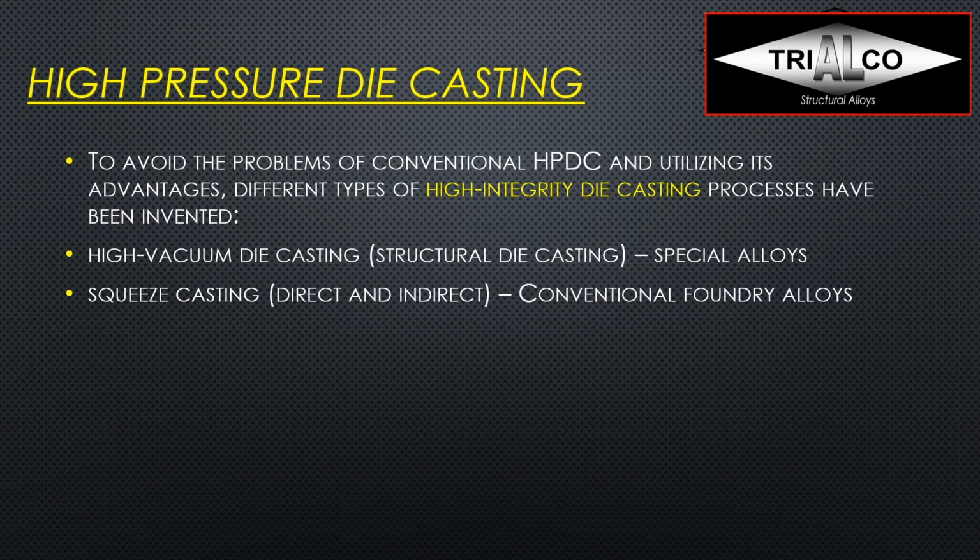And then we have the semisolid casting. There as well, you can use conventional alloys, but the beauty of semisolid casting is actually that we can cast different types of alloys as well that are much more difficult to cast. Semisolid is really just the way it sounds. You have a certain solid fraction that can be relatively low, just 20 or 30%, but also even 50%. So 50% can already be solid, and then the rest liquid, of course. This is nicely mixed and then squeezed into the die. The question is now, how do you get to this semi-solid status? It's almost like a soft butter that you're injecting into the die.